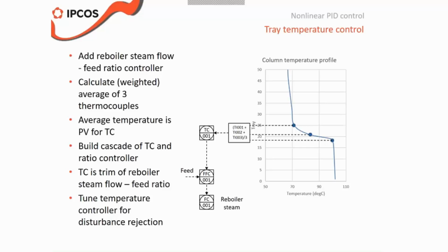That will give you a linear model, and then plot the prediction of the model and the actual pH measurement against each other, and that will give you the characteristic, very similar to what you could also do for nonlinear qualities. If you have a distillation tower, you want to control the top quality in an APC controller, which is nonlinear. That's also how you build a transformation for an APC controller. Plot the predicted value and the actual value against each other, and that will give you the characterization.